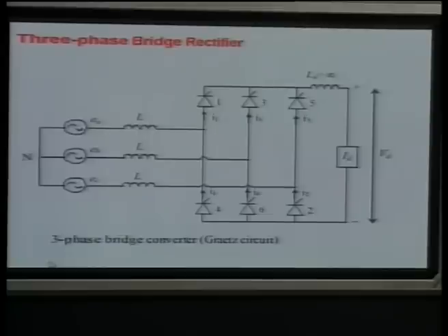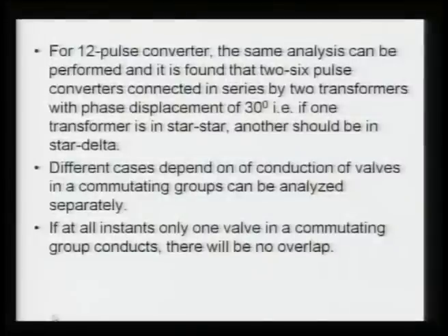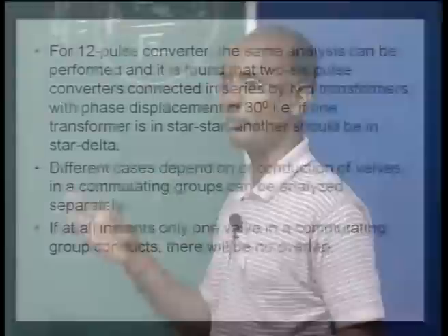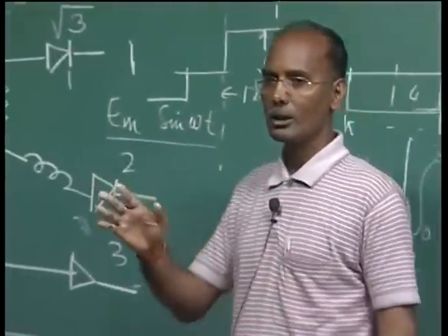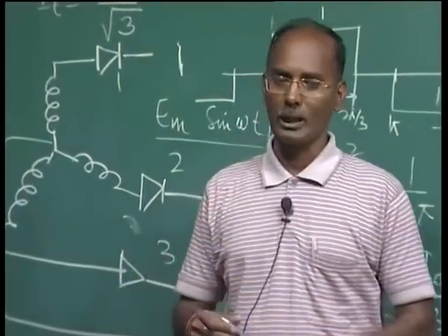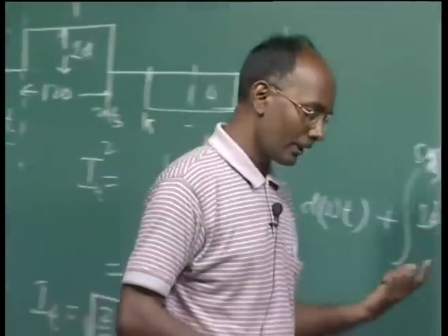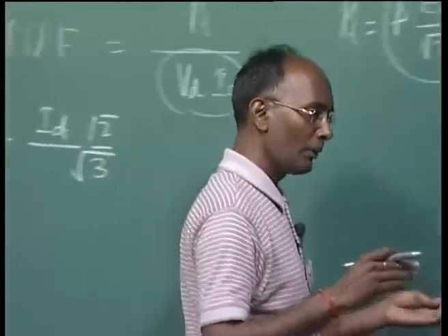Now, in this analysis, one very important thing is that the phasor concept should be very clear. Before that, we will see that the same analysis can be repeated for the 12 pulse converter. Whatever table I have represented for the 6 pulse, you can again write for your 12 pulse, and you will find that Q equal to 3 will be optimal.